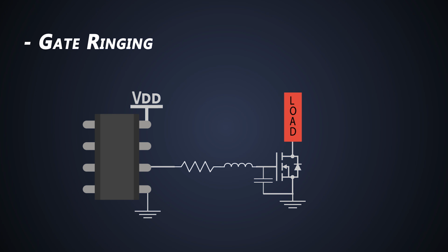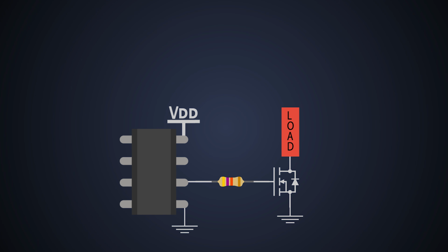For power MOSFETs, this gate ringing effect becomes more severe. To avoid the gate ringing effect, we use a large gate resistance, which will increase the damping effect and finally suppress the ringing. But again, increasing the gate resistance will decrease the efficiency. Also, too high gate resistance will decouple the gate signal which comes from the output stage of the driver. This will lead to longer delay times or even operation failure. Therefore, the value of the gate resistor should be chosen very carefully.